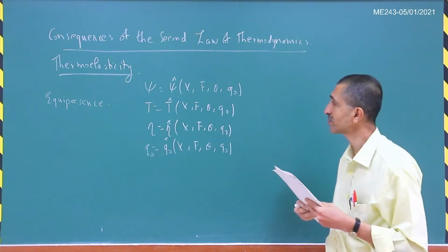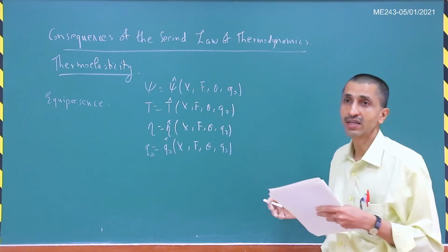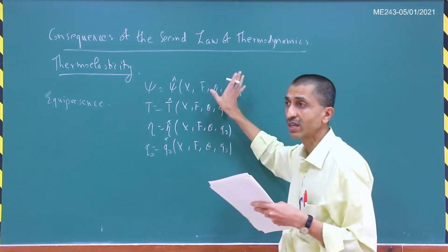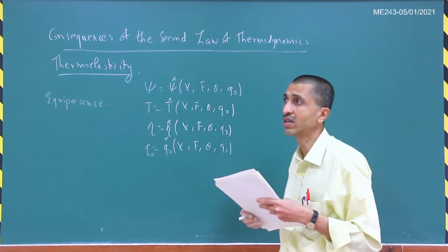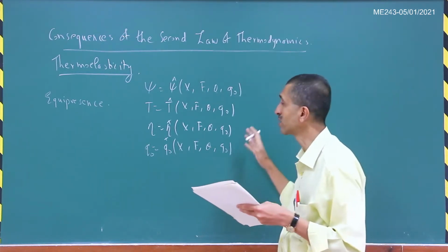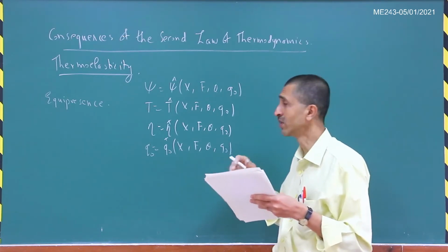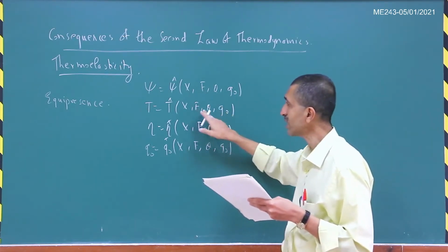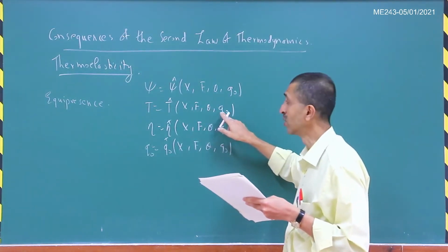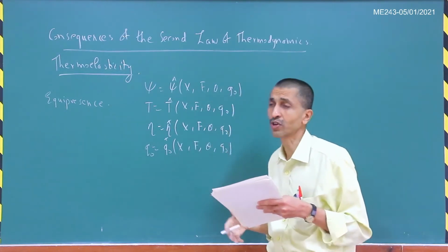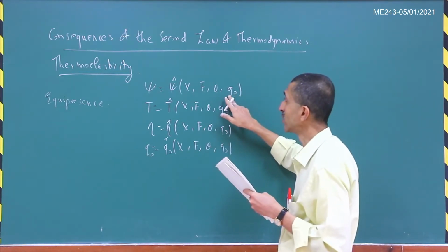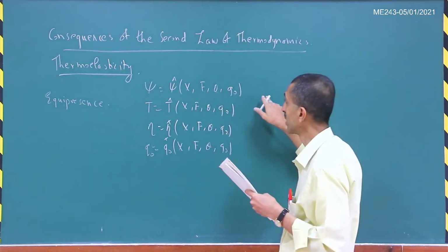The other important thing is, how do we decide this kinematical list? This kinematical list is based on our experience with that particular kind of material that we are studying. For the case of elasticity, we know that the stress will depend on the deformation gradient, the temperature, and the temperature gradient. Suppose you are studying some new kind of material, then in that case you would need to know what the kinematical variables are.